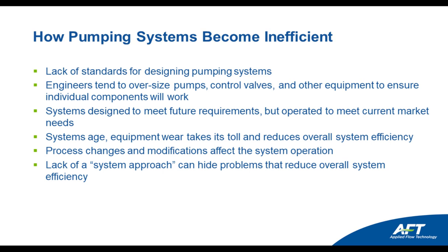The lack of standards for designing pumping systems is a big reason why systems become inefficient, because they're not taking a system approach to seeing how the pumps are going to operate when all of the rest of the changes in the system are occurring. When that happens, pumps and control valves can become oversized.